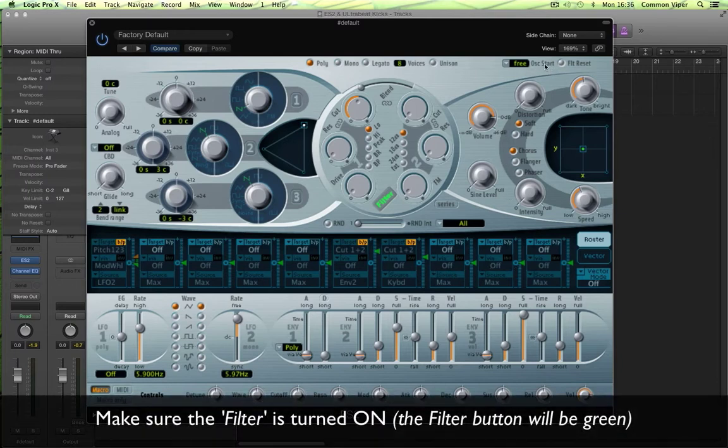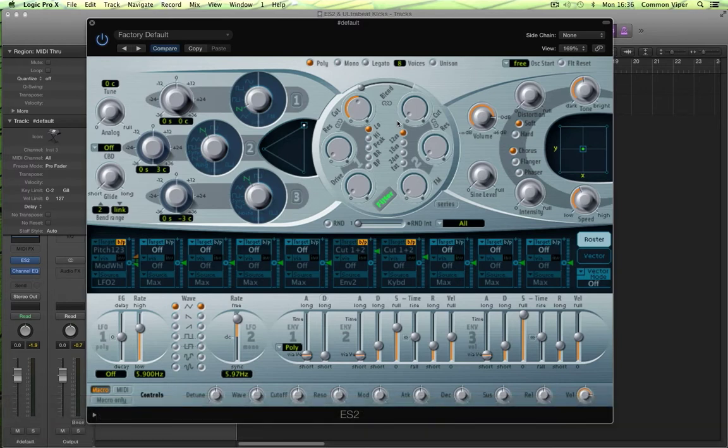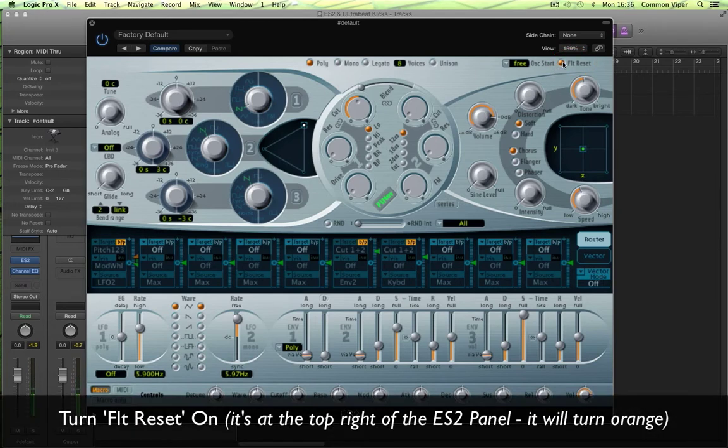Now the tiny bit of noise comes from analog synthesizers where there was already noise in the noise floor of the electrical analog equipment, and it would feed a tiny bit of noise into the filter. And then when you boosted the resonance, it would boost that noise at a real peak, which creates a ring. Now listen to this, I'll feed the bit of click. Here it is, I have to put filter reset up here, and that feeds a tiny bit of noise. Hear that? Tiny bit of noise into the filter.